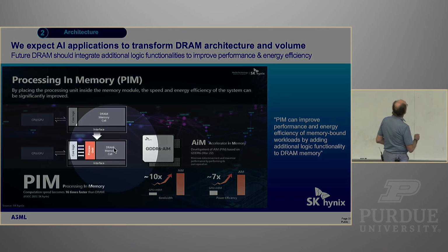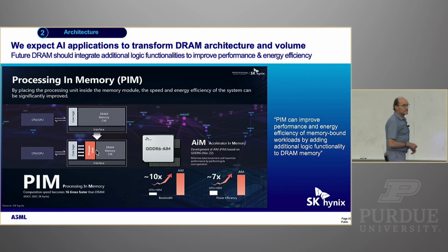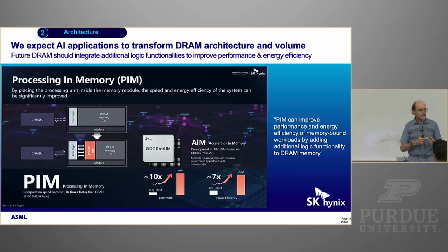teach my memory chip to do some of the computation itself and only communicate the results of the computation to the CPU? Now, what operation would I want to teach my memory to do? Whether I do a matrix multiplication, or tensor calculations, or Fourier transforms, or convolutions, or convolutional neural networks, the basic operation is always take two large columns of data, multiply them with each other, and add it up together.